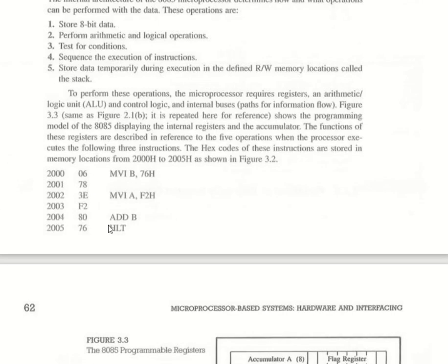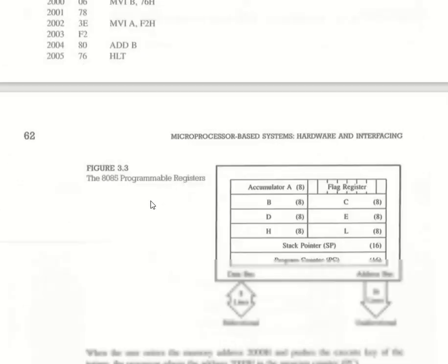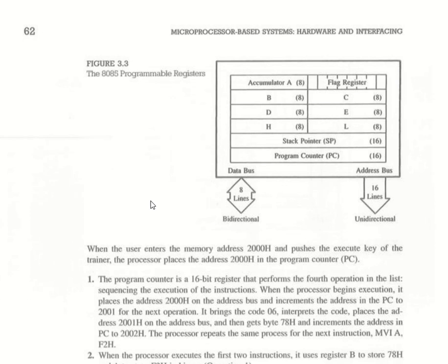See, we are having add. So what does add do? It sums both of them. So we will get the result. It will replace the F2h, which was previously in the accumulator, by 6Ah, sorry, 6Ah, which is the total sum of both of them.